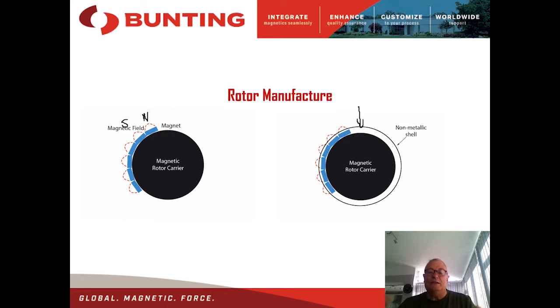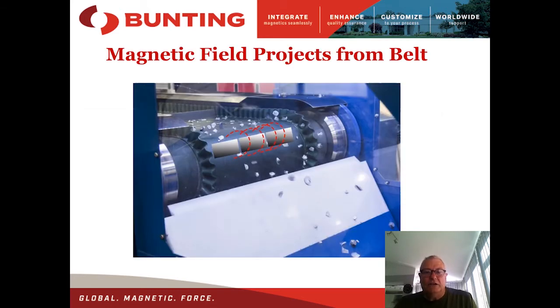So once that's in place around the side of the magnet, then the magnetic shaft itself is sent for balancing to ensure that it doesn't flex, or that it's stable, and the weight distribution across the whole width of these units, which can be very wide, well over 1 meter in width, sometimes up to 2 meters in width for some applications. So it's essential that they are balanced and the weight distribution is even to stop any flexing during operation over the lifetime of the unit.